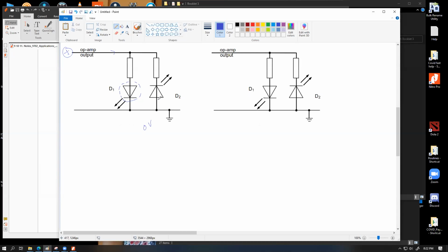For example, I mean, my point is that you shouldn't be viewing this LED's performance over a very large distance. People have to observe or be alerted by these LEDs from a pretty close distance, because they shouldn't have too much power, because this current has to come from the op amp. And whenever this is positive and this is the negative connection, current cannot essentially flow through this pathway, because current will try to go this way and this pathway will be blocked, so this will not be glowing.